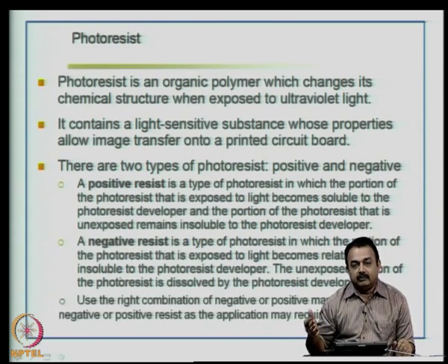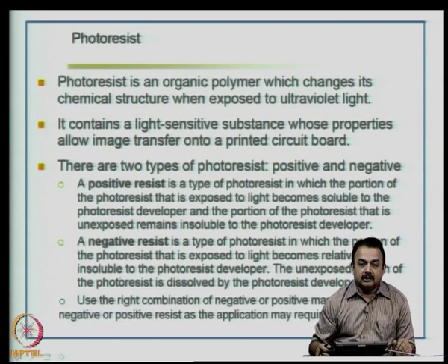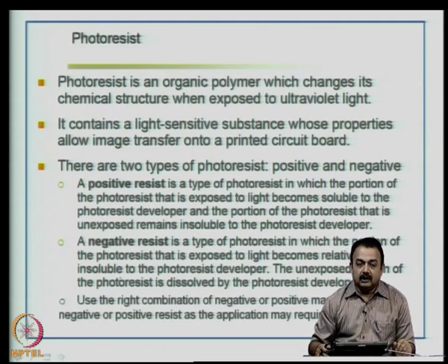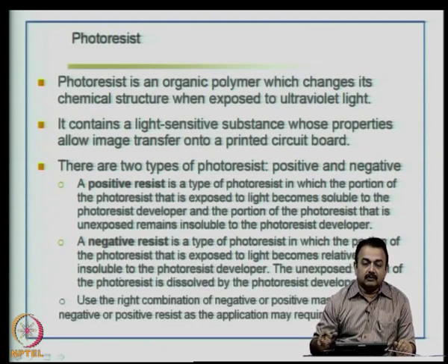On the one side, if you recollect, in the semiconductor industry also we are using photoresist material right now. There the line widths are much smaller. Today in the circuit board industry also we are moving towards 2 mil lines. Currently 4 mil is a very good leading edge standard, and imagine we are going to work on 2 mil lines.